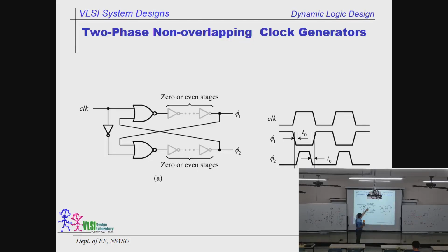Okay, they are identical. So the longer the stages, the longer the time in between. I guarantee this will work because many of us students use this way to generate the delay, as well as a non-overlapping clock. All right, it is a little bit complicated, but it is safe. It guarantees it will work. Okay, if the dead time is not long enough, you just increase the number of stages over here. That's it. Make it as long as you like, as long as it fits the requirement.